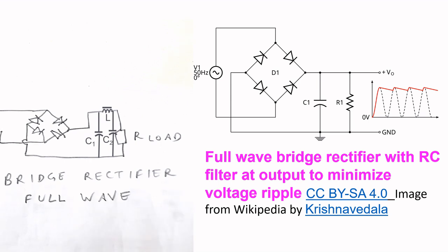The full wave rectifier utilizes both halves of the input alternating current cycle using two diodes, unlike the half-wave rectifier, which utilizes only one half cycle with a single diode. Hence, the full wave rectifier yields higher voltage output. The conversion ratio of a full wave rectifier is about 81%, but a center tap transformer is needed for this type of full wave rectifier using two diodes.